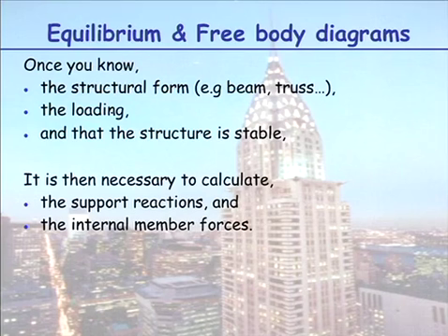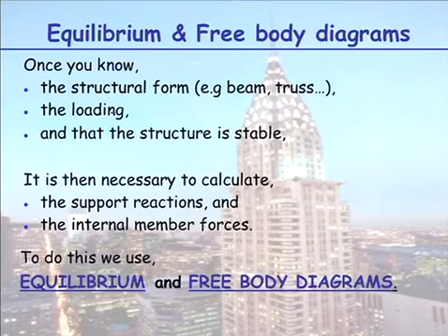Okay, so we know all about structural forms, beams and trusses, what they look like. We know a bit about loading now, and we know that a structure has to be stable. What we're going to do now is firstly calculate reactions and then internal member forces. So we're going to focus on reactions this week. What's the next step? Before you can calculate deflections or any internal stresses, the first thing you have to do is calculate reaction forces. And to do that, we use equilibrium and free body diagrams.